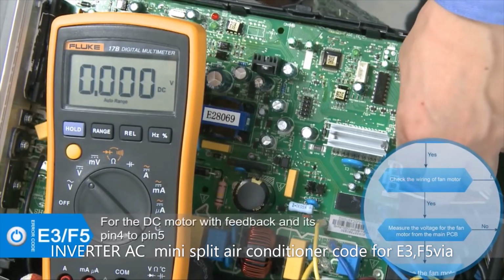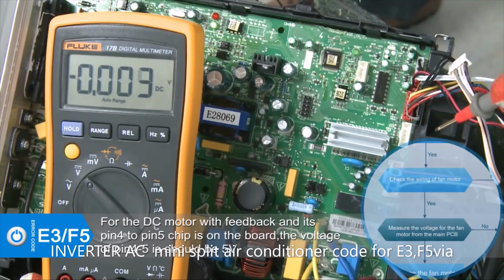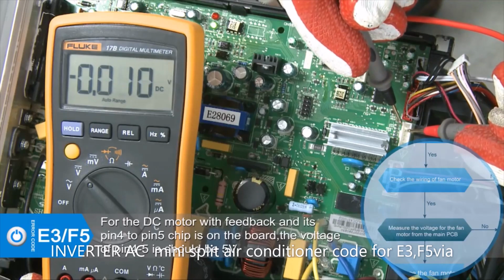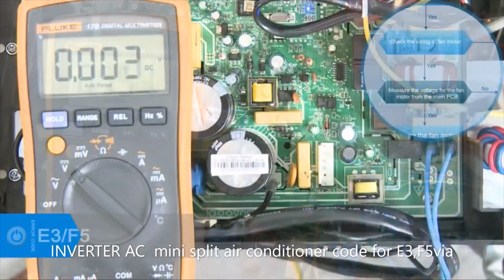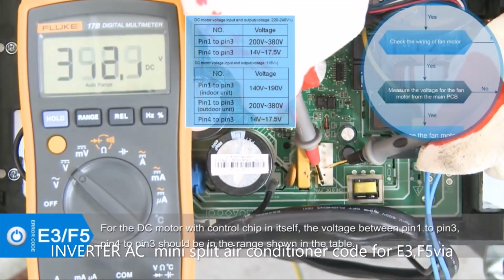Examination for main PCB board. DC motor with feedback and its control chip is on the board. Turn the power on. When the unit is in standby mode, measure the voltage of pin 4 to 5 in feedback signal connector.